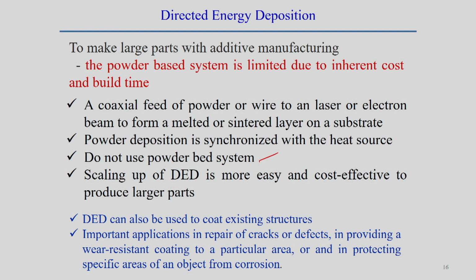Of course, DED can also be used in some coating technologies that we discussed in the first part of this module, the different coating technologies. So, DED can also be used to coat an existing structure, in coating applications, for repair of cracks or defects, for providing a wear resistance coating to a particular area, or for protecting a site specific area of an object from corrosion. For that purpose also we can use directed energy deposition. This process is more or less equivalent to the laser cladding